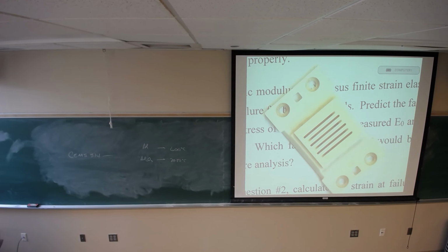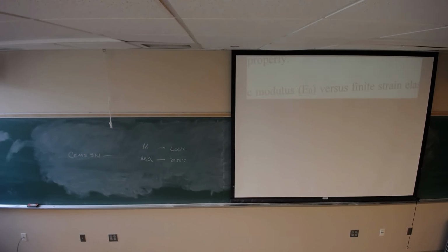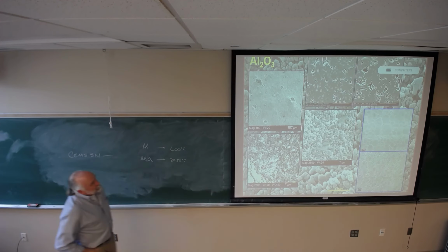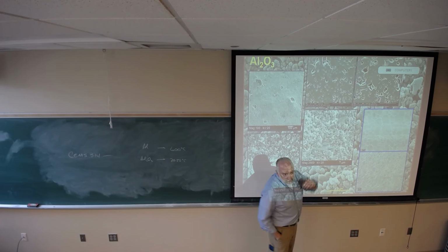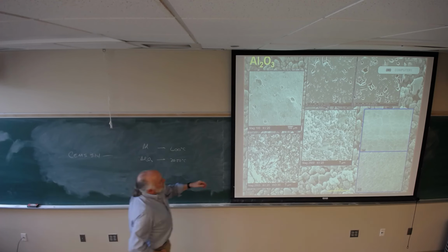I'll pass it around. It's made out of alumina, and they were making 250,000 of these a week for printers at the time. And they had an interesting problem, and the problem was that right along here in injection molding, along this line, it would crack. And we solved that problem. It was cool. The reason it cracked was what's called shear-induced segregation. And the reason was the temperature was too high and it reduced the viscosity and caused segregation. These are great because the upper right 2 inches are tabular alumina, which is an industrial alumina. There are 3 forms of alumina we typically see. These are examples out of the 203 class.